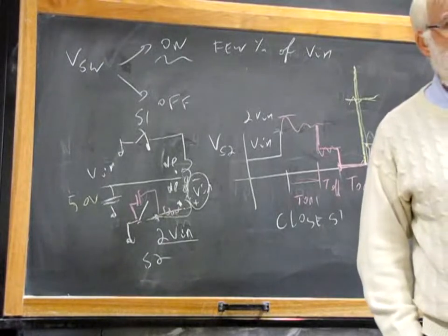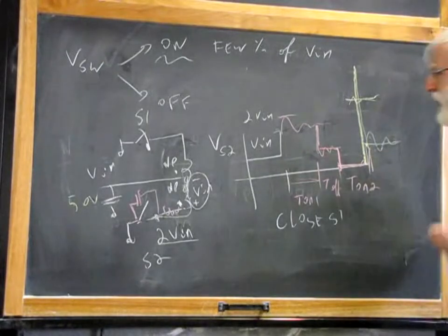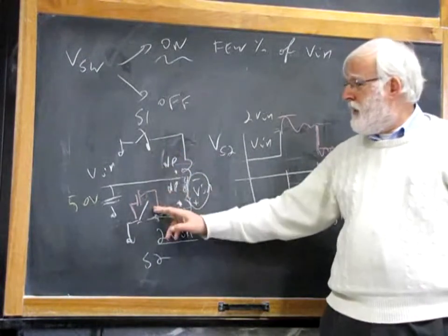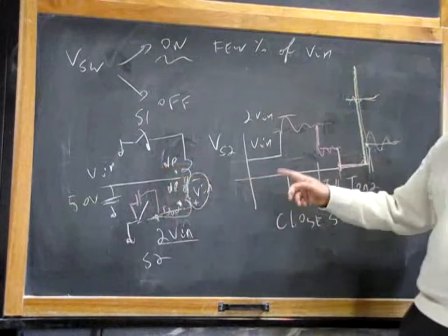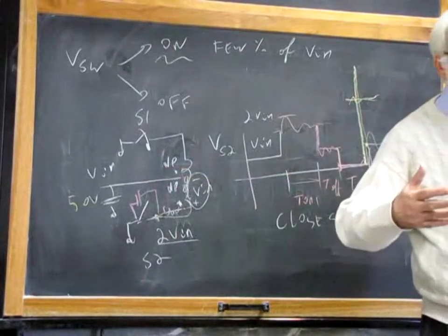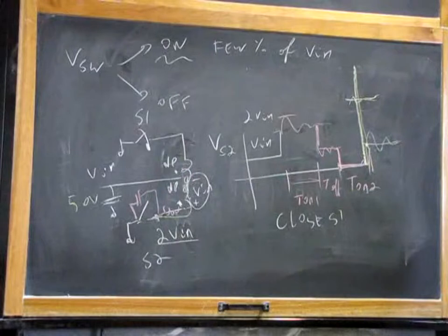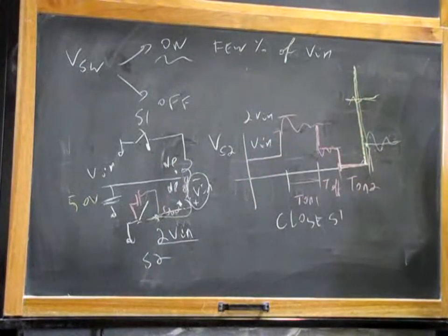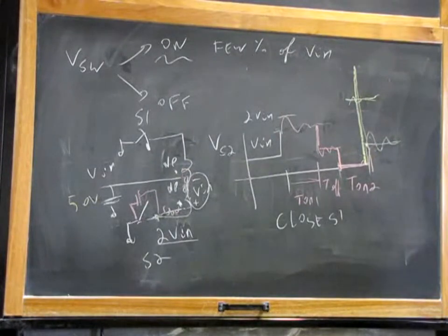A good way to boost up the car voltage is to use a push-pull, because this is the ideal topology for low input voltage, and with the turn ratio you can get an output voltage that is plus minus 50 volts, positive and negative 50 volts, to supply your amplifier, with a power that is a few hundred watts. This is the ideal converter for audio amplifiers in a car. Because the input voltage is low, the power required is 100 watts or so. This is what you usually do. Okay?